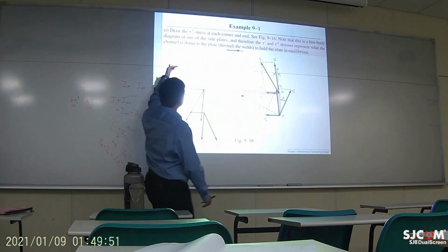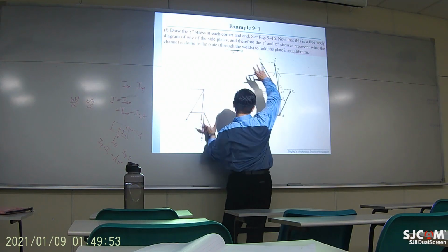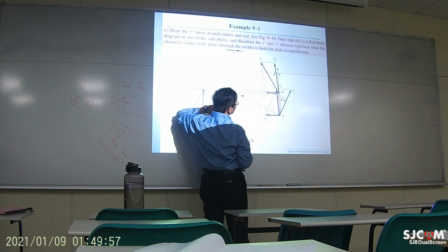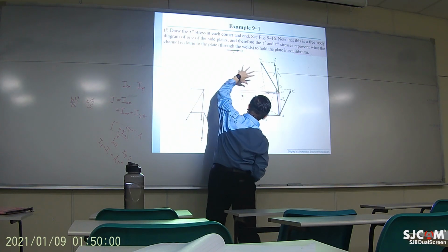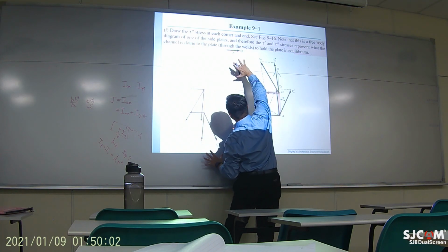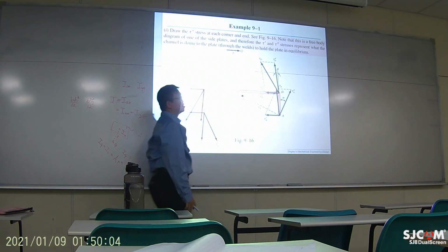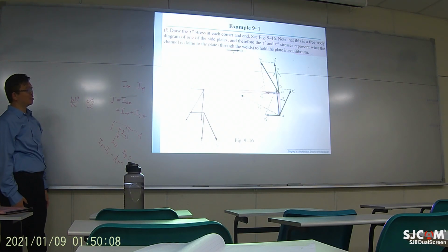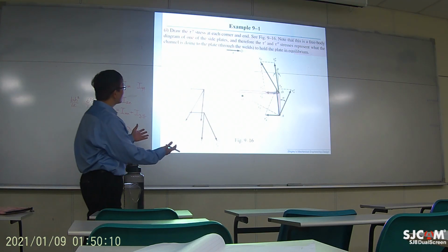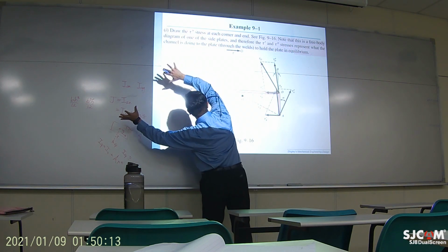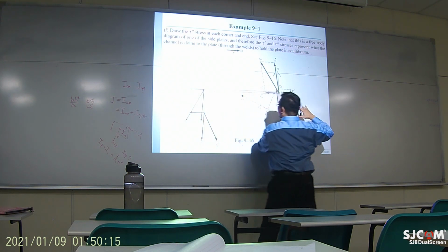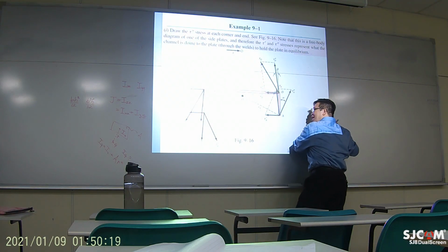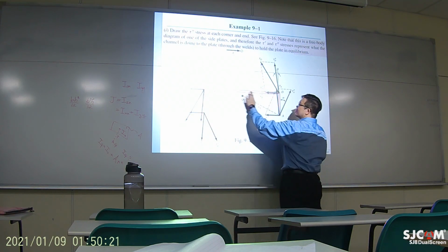Okay? So this is an external force going like clockwise. So all the stress due to reaction forces are going counterclockwise to balance out the one that was applied externally. Okay? So over here because of the force going left to right, there will be a shearing stress going right to left everywhere.